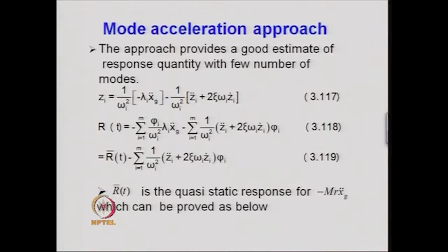Therefore, the classical mode summation approach, that is the classical modal analysis technique, is improvised to obtain a method which is called the mode acceleration method. It is found that this mode acceleration approach provides a good estimate of the response quantity with a few modes, and the reason for this is shown over here.